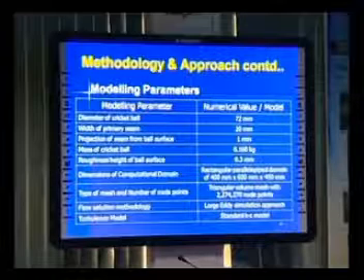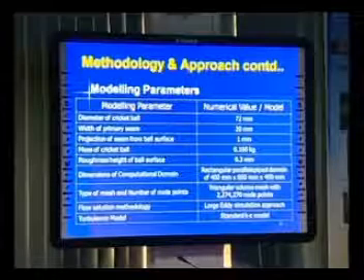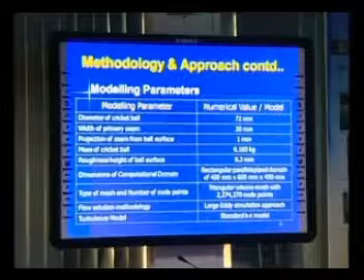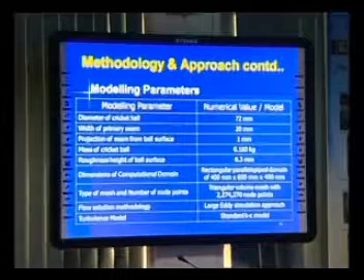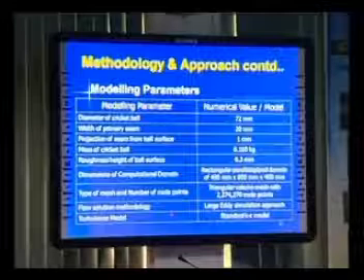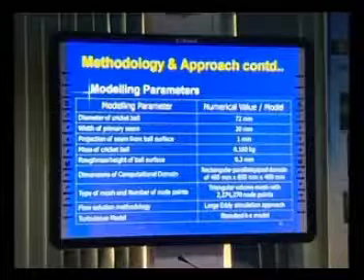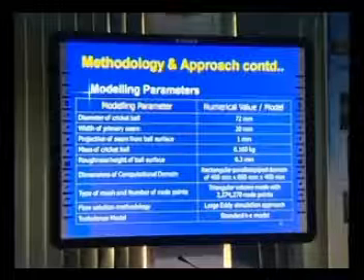Million node points. So it's a huge number of node points. At each node point, all the transport equations are solved in each iteration. Flow solution method: large eddy simulation approach, a CFD technique. Turbulence model: again, the standard k-epsilon model was used.